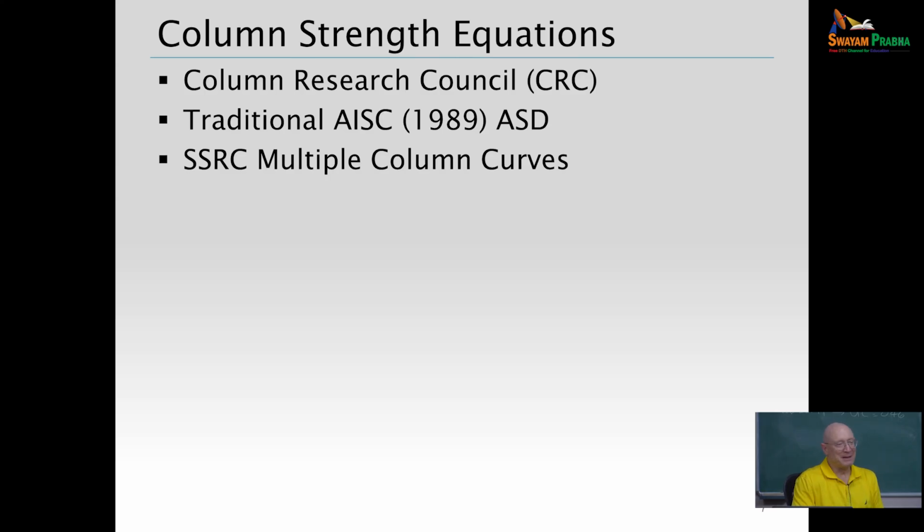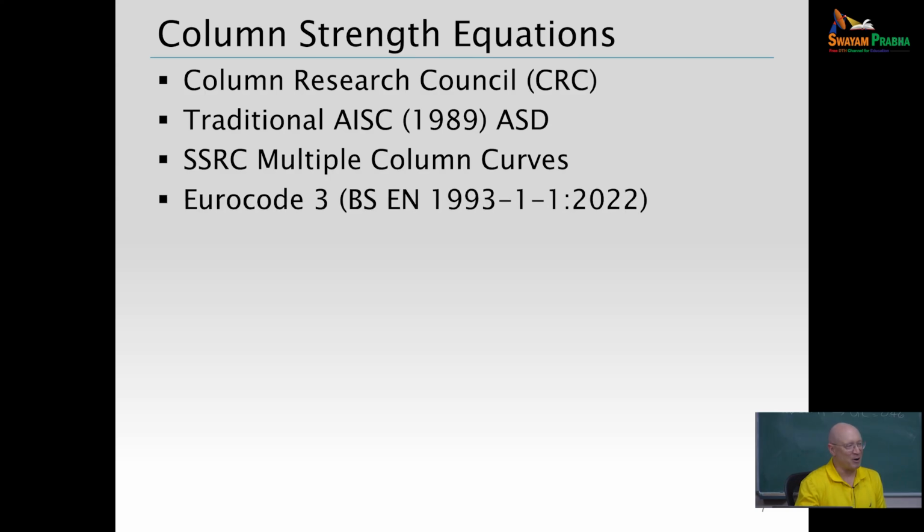And even now, in the technical committees at AISC, we are discussing quite intently that, particularly nowadays, we may be looking at instances where we want to use very high strength steels. You pay a huge penalty if you don't use a different column curve if you go to a higher strength steel. So at least for that, we at AISC have some traction that we should have maybe two column curves. You can still make arguments for the others, but it's a hard sell in the AISC committees.